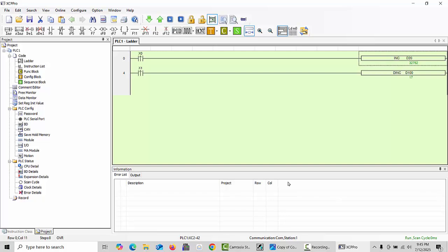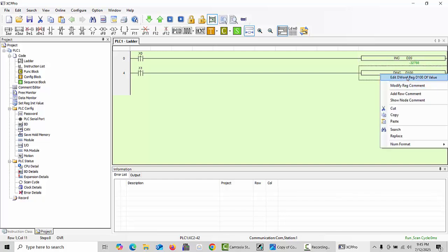And now I will give the signal at X0. This is the 7, it starts the value from 32,763 because I put the random value, 4, 5, 6, 7, and as you give one more, you can see the minus value coming, minus 32,768. So that command does not support big values.